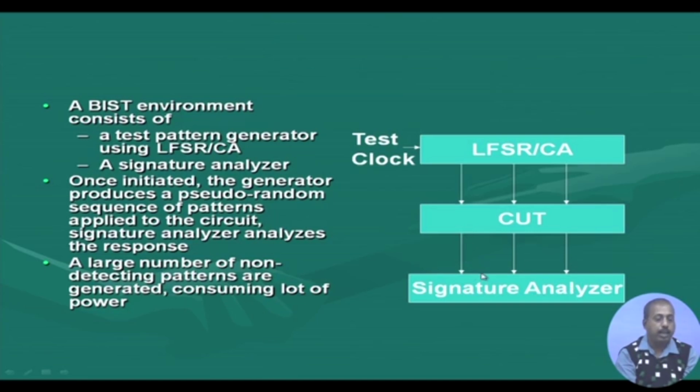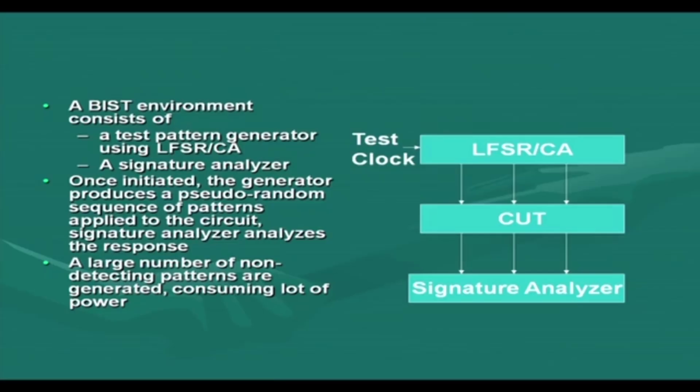That is the whole idea of this BIST based approach, but the difficulty is that maybe we apply the first pattern and it detects a number of faults, then we apply the second pattern. During fault simulation we find that the second pattern does not detect any new fault. In the ATE based approach, we can simply not apply the second pattern to the circuit, but here that facility is not there, because I cannot stop the LFSR from generating the second pattern.